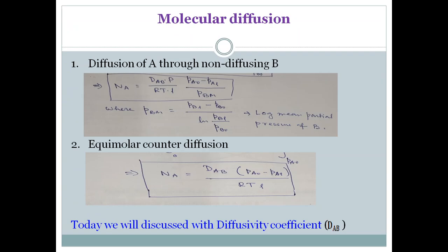But you can increase only to a certain level, because if you increase the pressure, your equipment cost will also be higher. You need greater thickness of the equipment, so cost will be higher. So there is a constraint. You cannot increase the driving force beyond a certain value, not ten times like that. Similarly, pressure and temperature you cannot take beyond a certain limit.